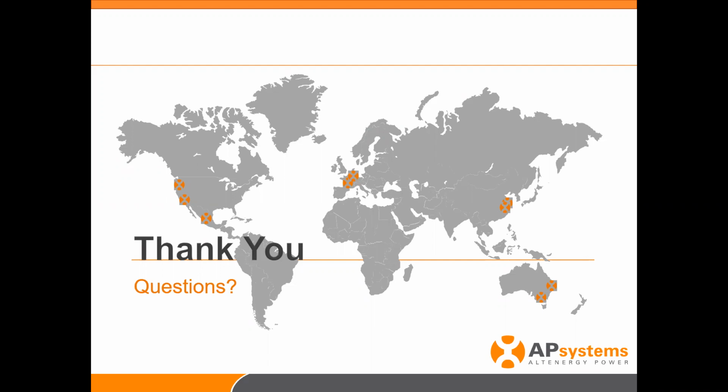Let's say, for example, I live in Texas and we do a lot of pole barns here. We do outcrops, barns, whatever, ground arrays, ground mounts, whatever you want to call it. In that particular case, when the distance is greater than 200 or 300 feet from the residence or from the internet source, then I will add something in there. I will put the ECU or gateway at the array in a weatherproof box, NEMA 3R or better, and then backhaul that information back to the router using what I call the AirWire.